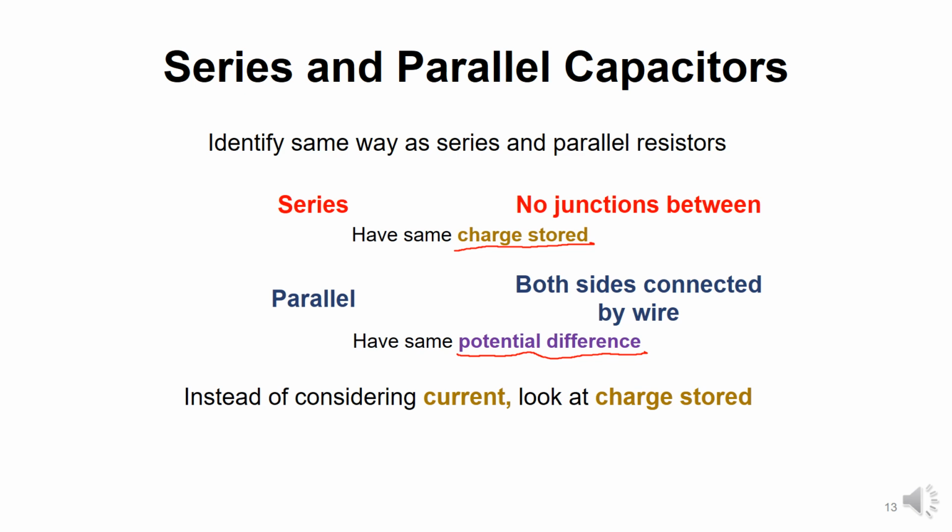So you can see that on the slide, we have the word charges underlined, charges stored, and we're not explicitly talking about current. Okay, so when we're trying to analyze capacitors in series or parallel, think of charges rather than current. Right, and the footnote at the bottom says that the charges are really carried by current, so you'd think that they're related, but nonetheless it's easier to think of the concept of charges.